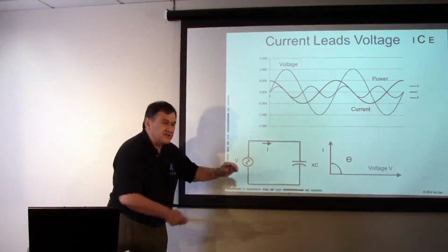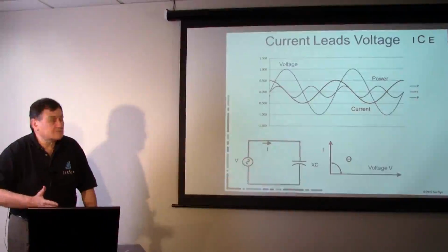And then as I build up that charge, my voltage starts to increase. So intuitively, with a capacitor, the voltage lags the current. You've got to get the electrons flowing first, charge up the plate, and then the voltage increases as those electrons build up.